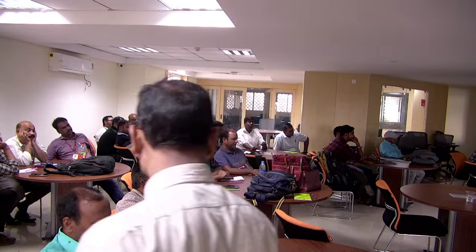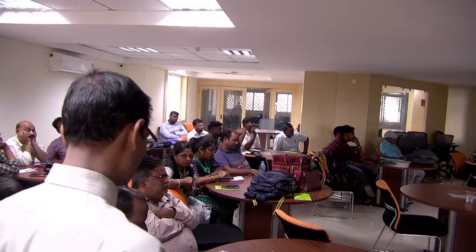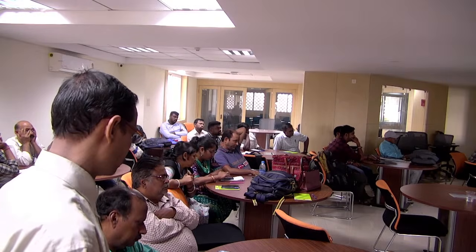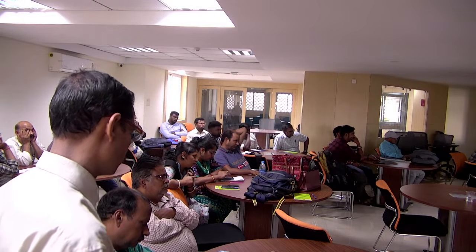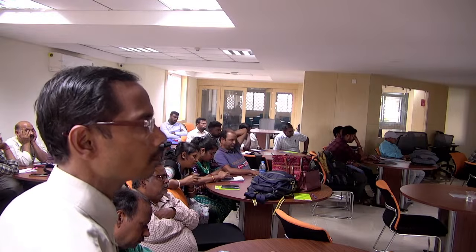Upon full load, machine 1 droops from 50 by 4%. Say, machine 2 upon full load has a drooping characteristic from 50 by 5%, right? Now you are combining these two machines to share a common load. Common load P1 and P2, common load must be shared.